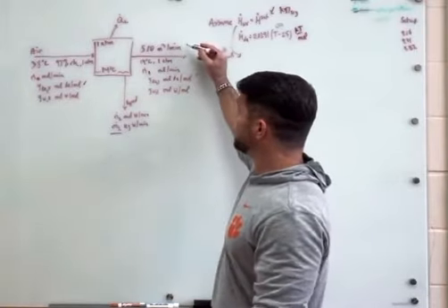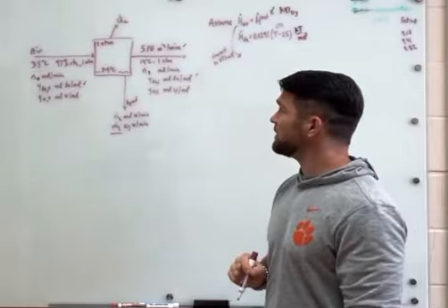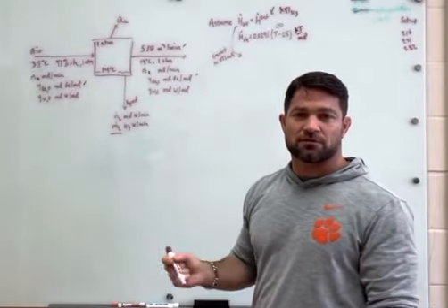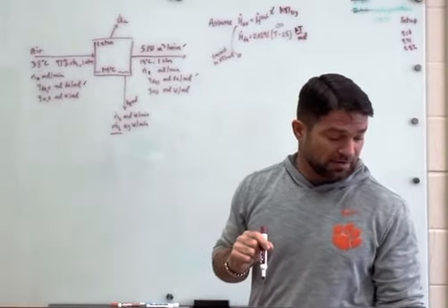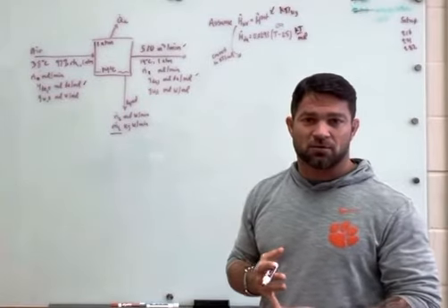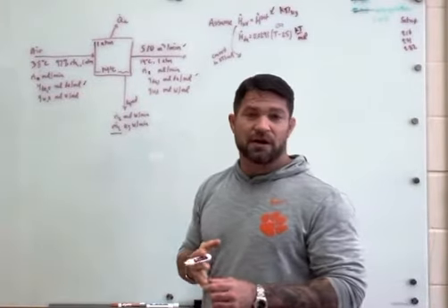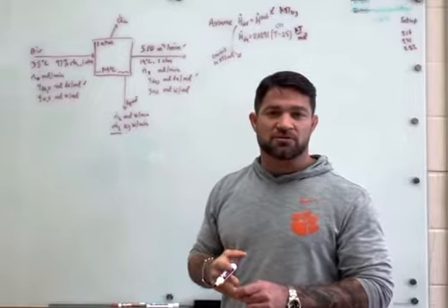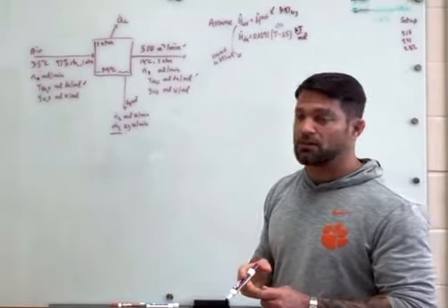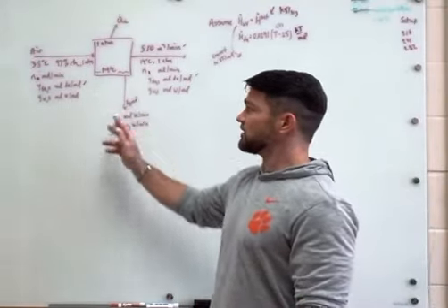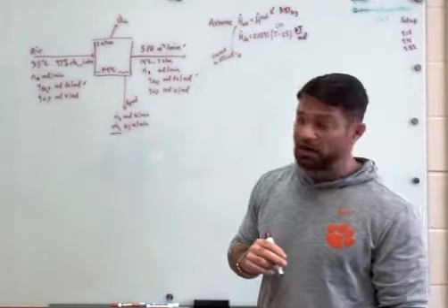I'm going to use the ideal gas law to convert the volumetric flow rate coming out into a molar flow rate. Then I'm going to do my mass and mole balances on the process. Finally, I'm going to use the energy balance to calculate the amount of cooling required for this process. All right, let's go ahead.